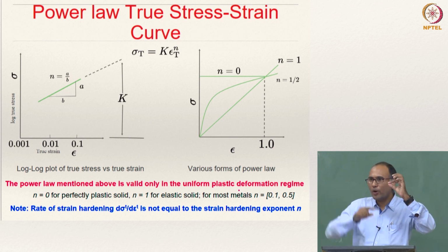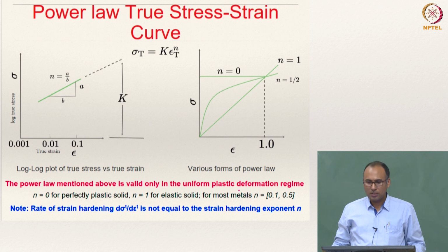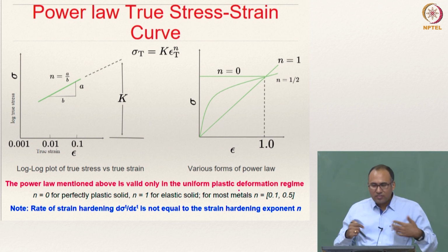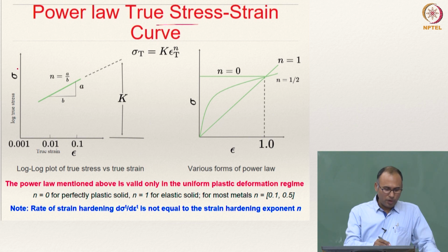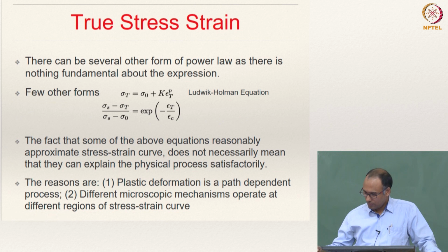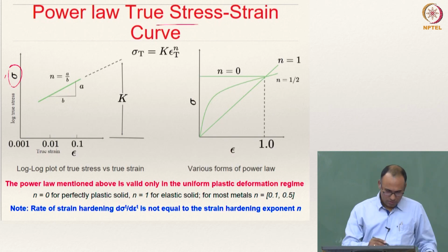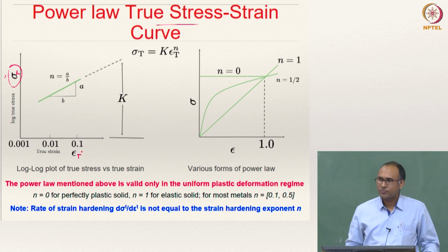And then how do we go about representing the hardening part? That means from the yield point to the necking, what is the functional form that we use, right. So, there are several functional forms that are available. Usually the power law is one of the popular models, wherein if you are plotting on the y axis, it should have been sigma t, because true stress and true strain.